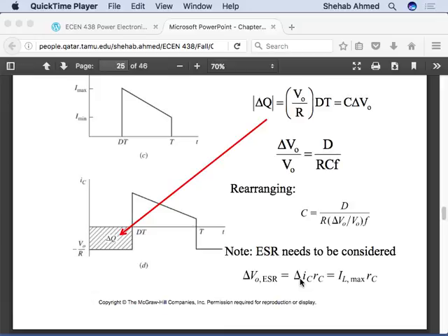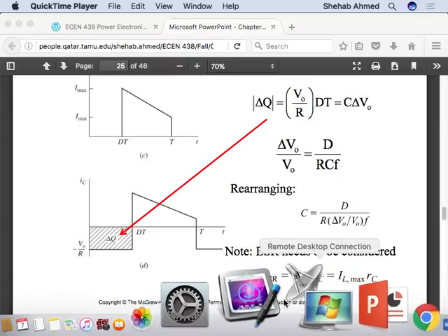So you assume the capacitance is big to be able to calculate the inductance, and then you assume the inductance is big to be able to calculate the real value of capacitance. Does it make sense? No, it's just that you assume the capacitance is big enough that all the AC components go to the capacitor, right?